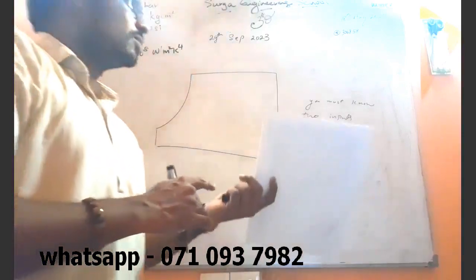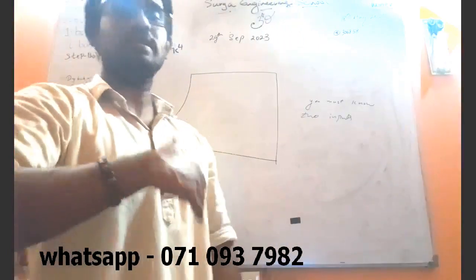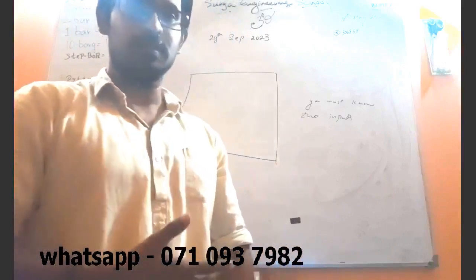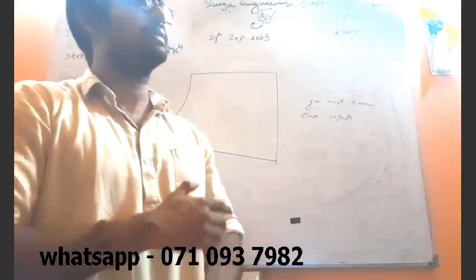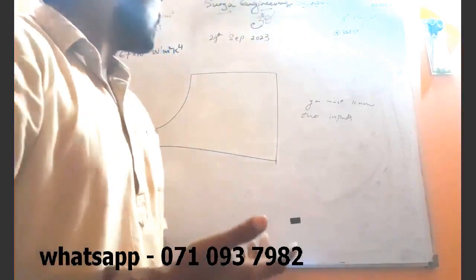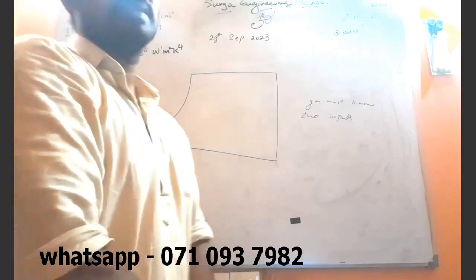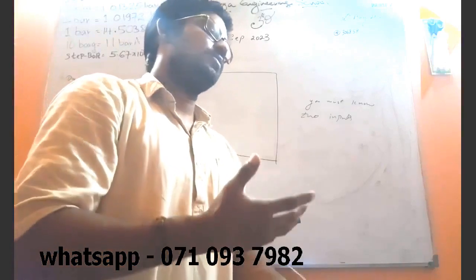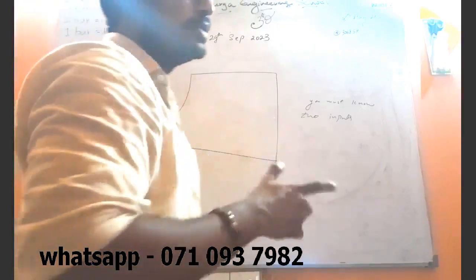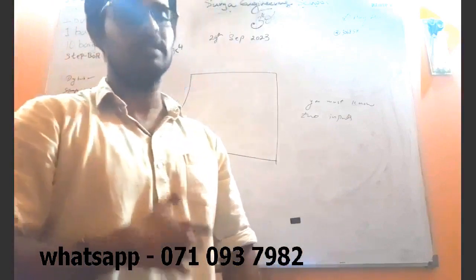What are the facts we have studied so far? We have studied humidity ratio, relative humidity, dry bulb temperature, wet bulb temperature, specific volume, specific enthalpy. There are many parameters. If you want to find the dew point, or any other parameter, using the psychrometric chart, be very careful: you should at least know two parameters. Without that you cannot proceed.